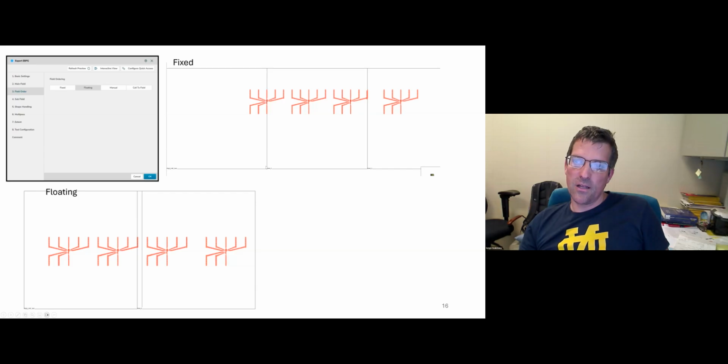The rectangle, this black line, is the boundary of a field. As you can see, the way it is set up, the field size goes exactly through the critical part of the sample. So one field is the left one, some part of the devices will be exposed there, then the stage moves, and then this part will be exposed. Now this device is fine because the whole device is in the center of the field, but this one is probably not going to end up well, or it will have different dimensions than you wanted to design.